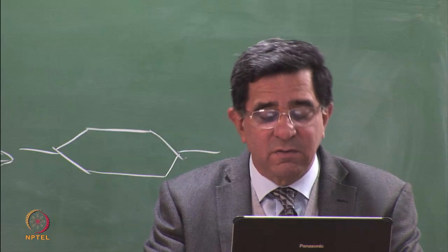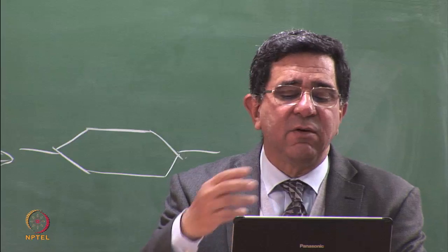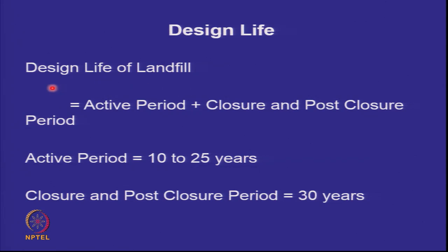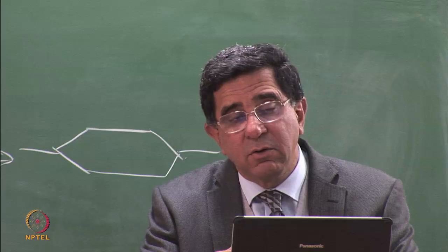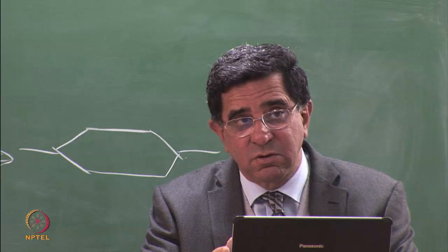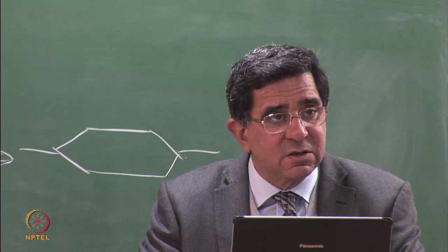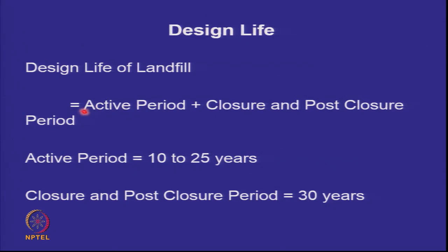If that much area is not available, what is the correct idea of the size of a landfill? The design life of a landfill is the active period when the waste is being filled plus the closure and post-closure period. After you have filled the waste and no longer put waste on the site, it is not closed, because the whole thing is still undergoing chemical reactions. So you have two periods, the filling period and the closure and post-closure period, for which you have to take very intense care of the site.